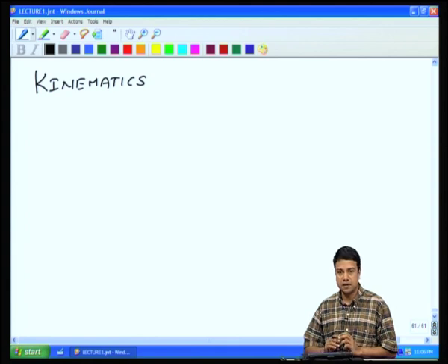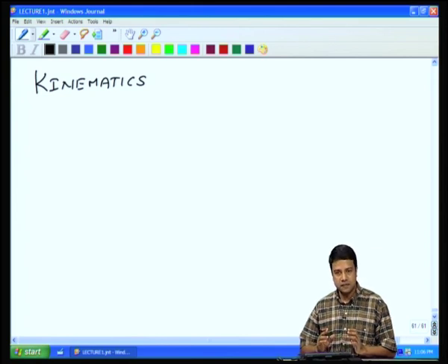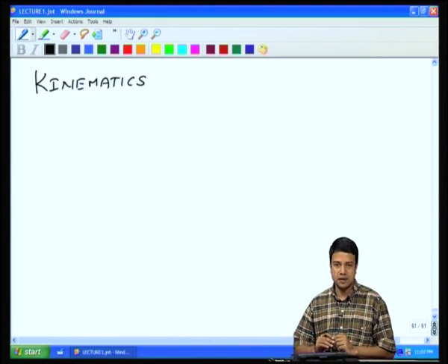In the case of heat and mass transfer, there was a concentration or a temperature field and there was a flux. The flux is a vector, it can be directed in any direction in space. However, it has just one direction. In the case of fluid mechanics, we have a velocity field and that velocity field itself has a direction. The transfer of momentum has a direction associated with the momentum itself, and a direction associated with the direction of transfer, and these two things come together.